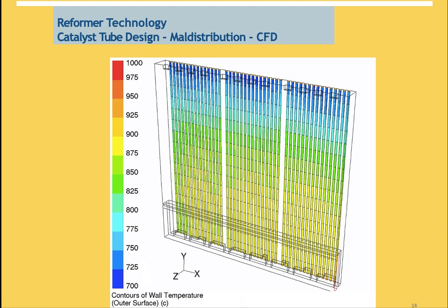The corrective action to protect the catalyst inside this tube is to increase the steam to carbon ratio immediately, increase the inlet temperature, reduce the feed rate, check the sulfur guard bed performance at R1, R2, and avoid rapid load change. Okay, to work right.